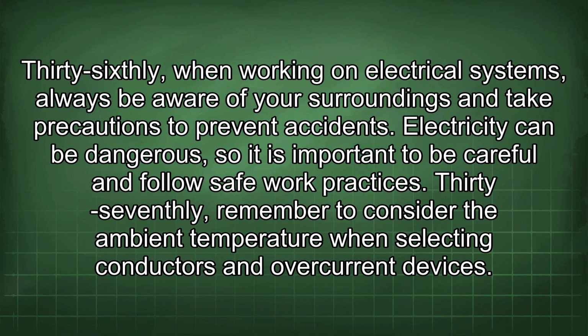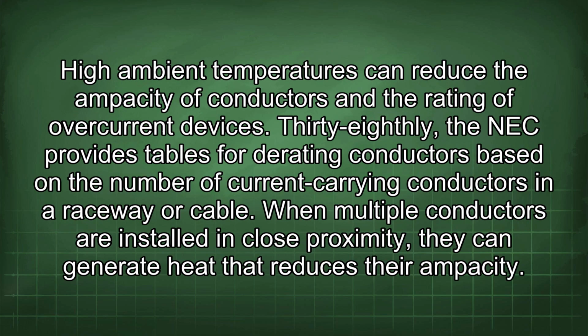36thly, when working on electrical systems, always be aware of your surroundings and take precautions to prevent accidents. Electricity can be dangerous, so it is important to be careful and follow safe work practices. 37thly, remember to consider the ambient temperature when selecting conductors and overcurrent devices. High ambient temperatures can reduce the ampacity of conductors and the rating of overcurrent devices.